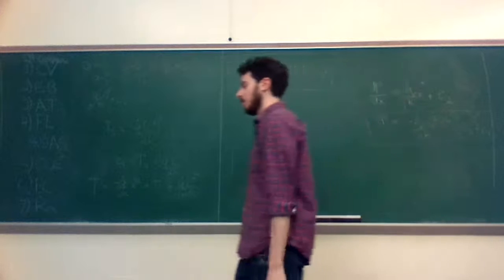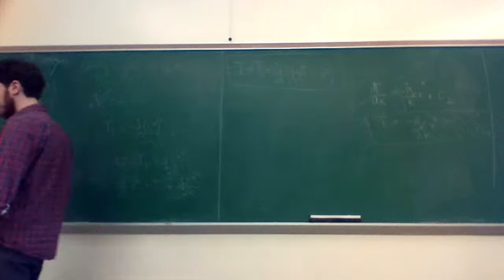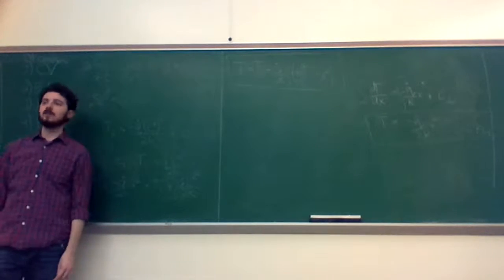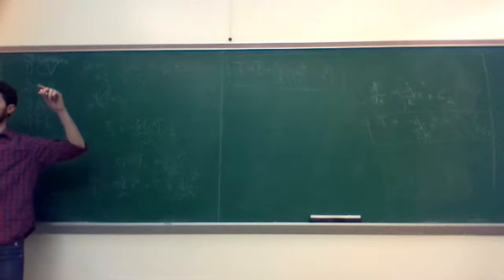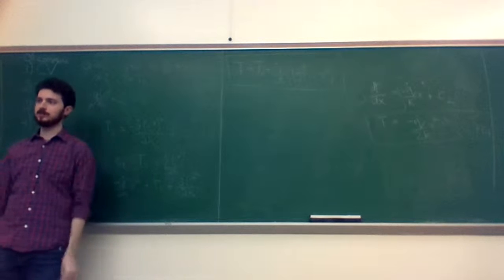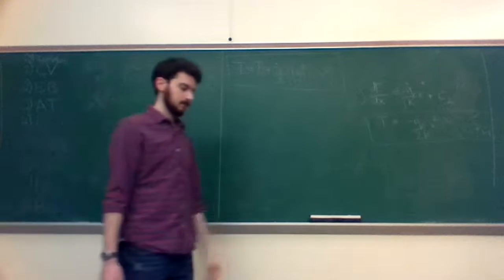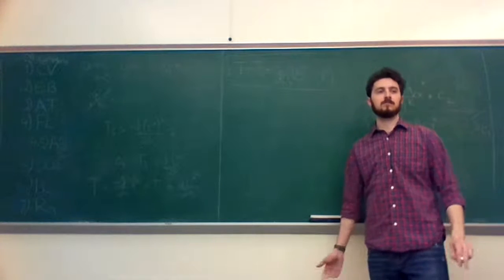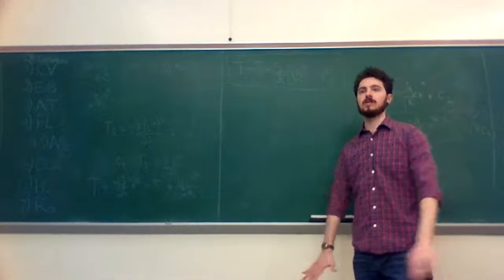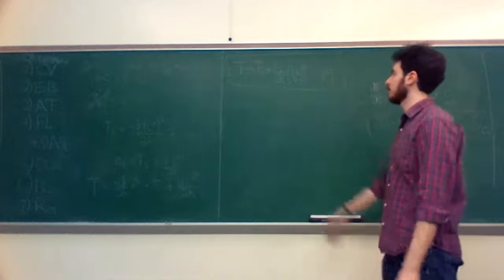The maximum temperature we believe is going to be at the origin. We can prove that with calculus, right? If we just differentiate that and then set it equal to 0, we're going to find that 0 slope place, and that gives us at least a local extremum. But let's just say that we all get the problem well enough to know that it's going to be at the center. We're not going to prove that right now.